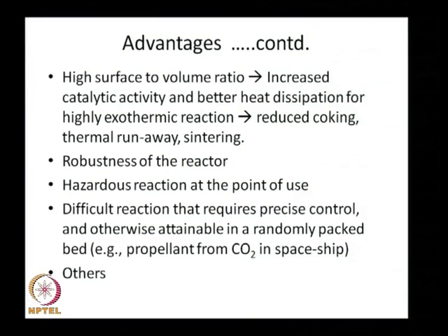If too much catalyst is there, then there could be extraneous reactions setting in, there could be thermal runaway, that means a lot of heat gets generated, and if it cannot be dissipated, then there would be sintering taking place, the catalyst gets destroyed, and also if unwanted products are generated, that will result in poisoning of catalyst.